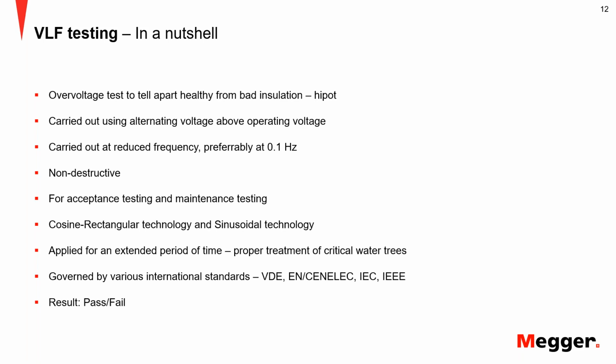Internationally speaking, the IEC world has a fixed frequency. IEEE allows for frequency reduction. VLF testing is non-destructive. That means it doesn't introduce additional weaknesses into the cable. There are two different waveforms. You have to apply it for an extended period of time, typically, specifically on service aged cables, because you want to treat the water trees appropriately. We will get to this in a second.